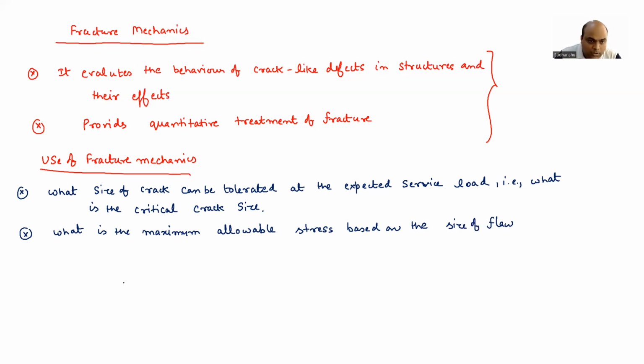That is point 2. Now point 3, you already have a crack. Say the length was L naught or A naught, because we will be using now A for crack length, right? A naught. After some time, crack length became A2. So you can calculate what is the time requirement from going from crack length of A naught to A1 or A1 to A2, okay, and so on. So that is point number 3.